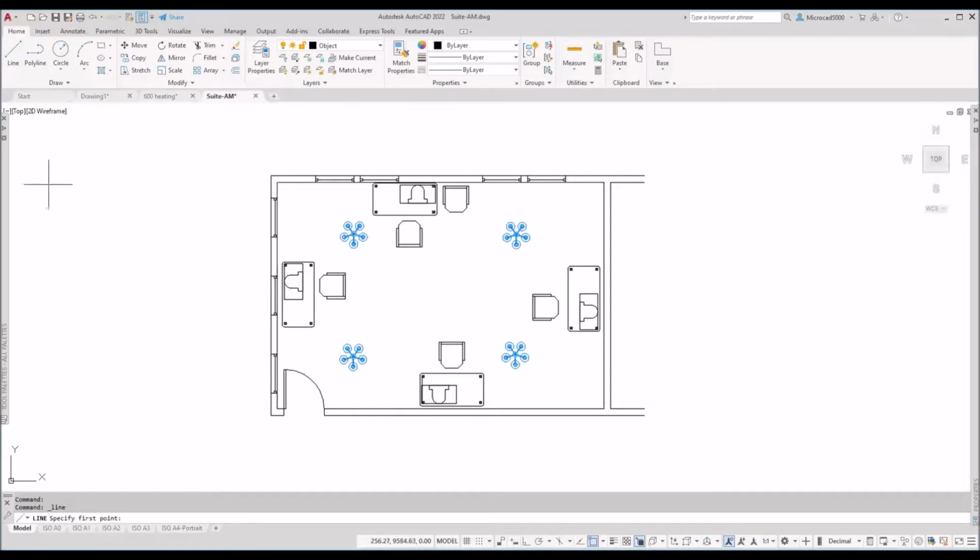Another option in there is if I draw some lines there, and then if I draw a circle there. Now if I go to the erase command and it says select objects down there, if I type in letter L for last, it picks up the last object. Hit enter and the last object disappears. I haven't found much use for that one. It's another feature, but that P for previous is quite good. But the L for last, well, okay, you could just go and pick on it, couldn't you?